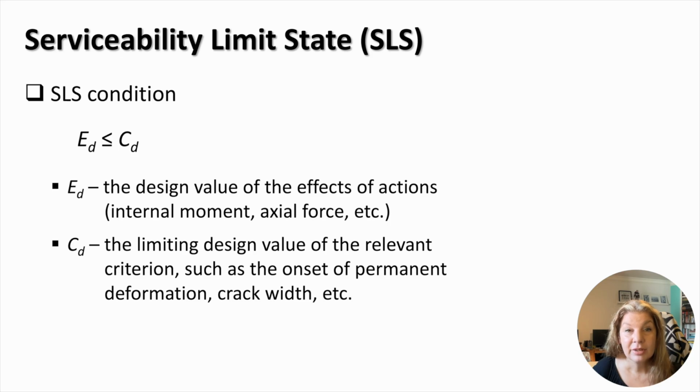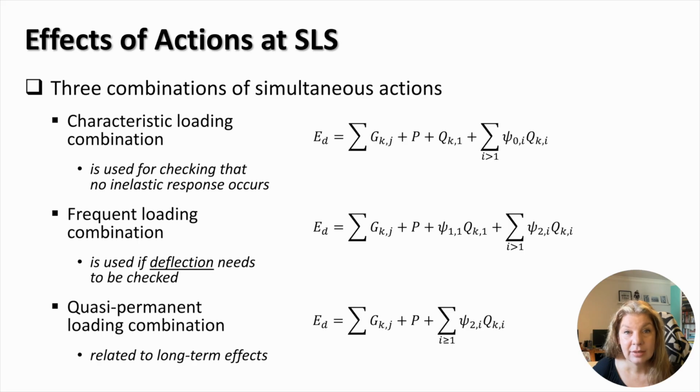The design for the serviceability limit state requires us to satisfy the following condition: that the design effects of applied action, that is, internal forces, moments and so on, are smaller than the limiting design value of the relevant criterion, such as the onset of permanent deformation, crack width, etc. The serviceability limit state considers several situations, including characteristic loading combinations, frequent loading combination, and quasi-permanent loading combinations.